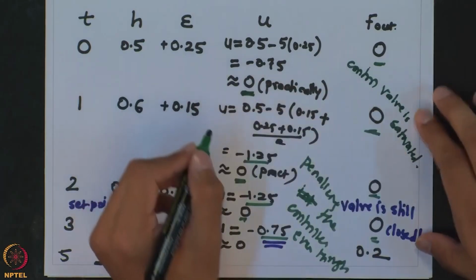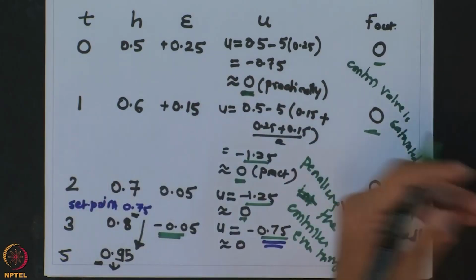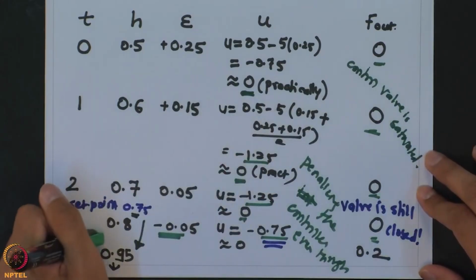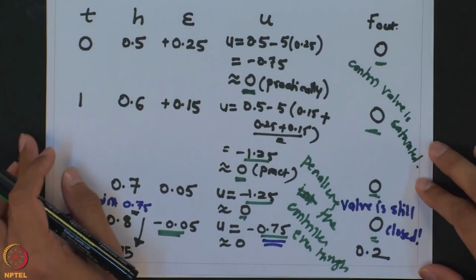So, in that case there is no point in accumulating the error, and this is the thing which is causing this high overshoot. This particular phenomenon is known as integral wind up. It will be present whether you have a PI controller or a PID controller.